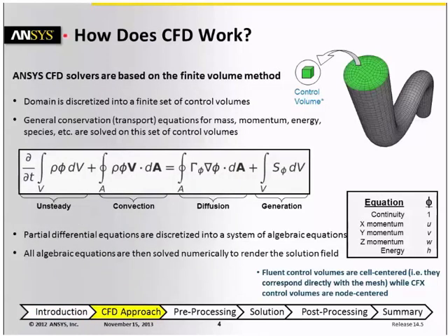Since we are talking about the CFD approach, it makes sense to begin with a brief description of how CFD works. The ANSYS CFD solvers are based on the finite volume method, and the way this method works is you take the system you want to study, this is also known as a domain, and you discretize it into a finite set of control volumes.